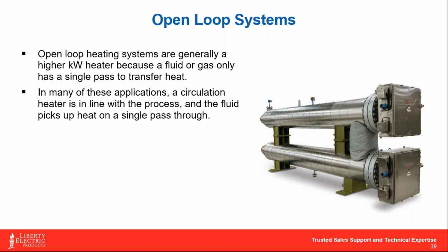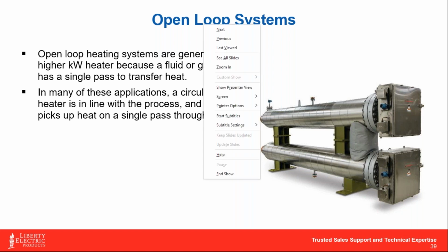If I recall correctly from my boiler days, an eighth of an inch of scale on a boiler was, I think, a 10% efficiency decrease. So it's pretty significant. It's just something you really have to watch when heating raw waters and things like that: the amount of solids that are in the water, and make sure that your elements stay clean.